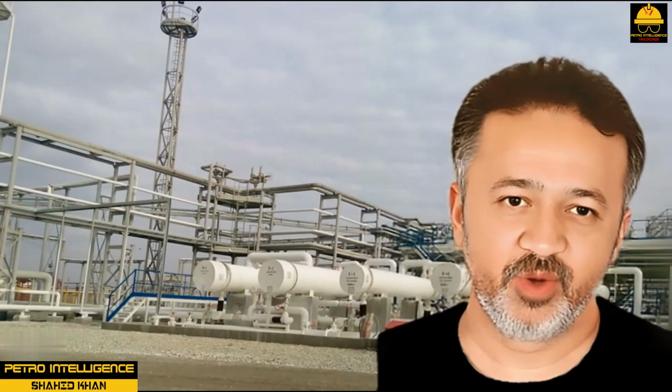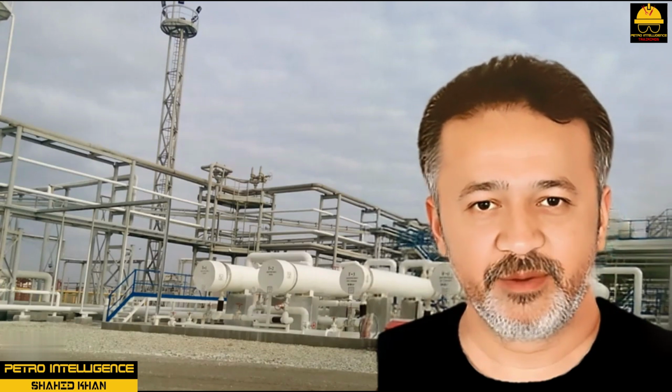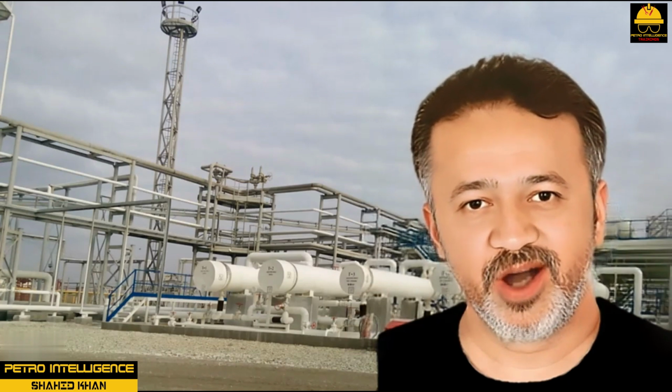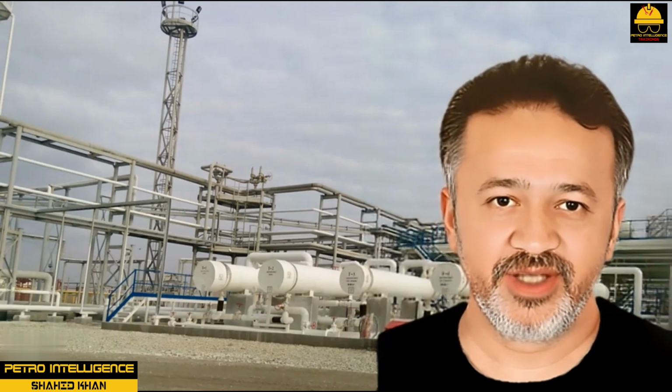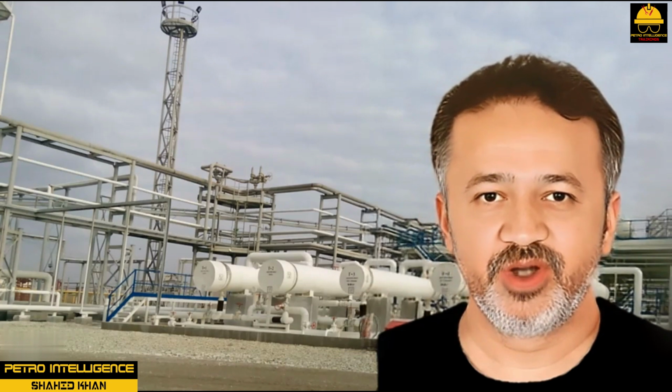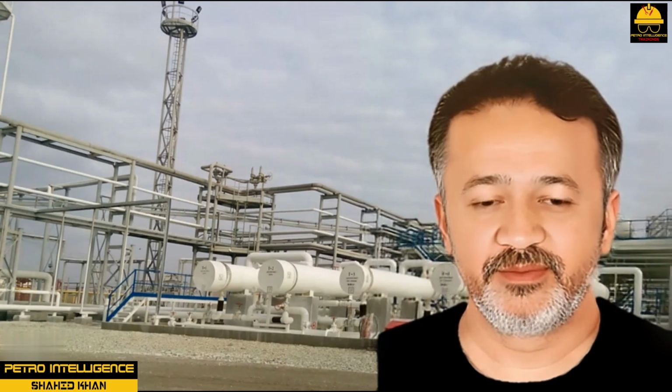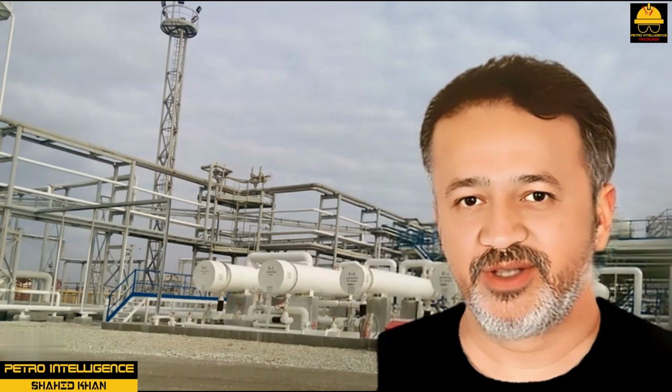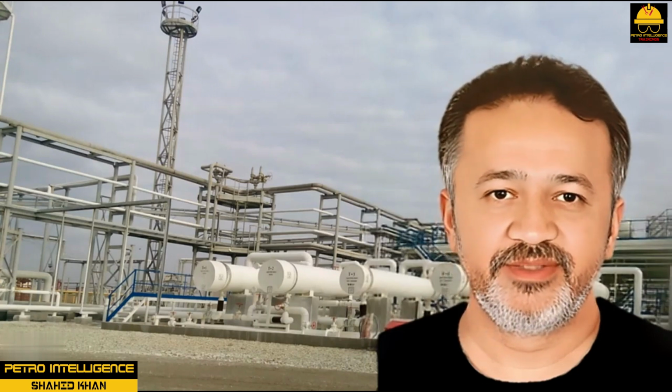Hot oil jacket reboiler. Some reboilers have specially designed hot oil jackets surrounding the bottom of the column. In this type of service, hot oil enters the outer shell and provides heat to the bottom product primarily through conduction and convection. The outer jacket functions like a heat exchanger as hot fluid circulates through the shell. This type of system is used on smaller distillation systems.